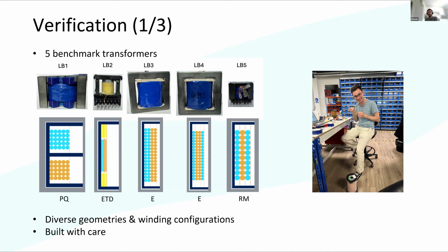And there is another question. Have you tried adding a negative dynamic resistance in series with the source circuit for the measurement on the secondary to reduce the effect of the series resistance during the measurement of the parasitic inductance? How would you add a negative resistor in reality?